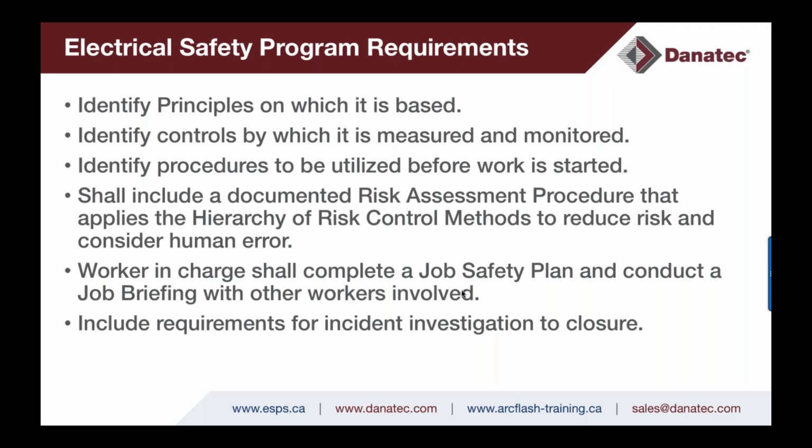The electrical safety program should include requirements for incident investigation to closure. So I find that this is not effectively managed. Companies do have overall incident management systems and their overall OHSMS systems, but what they lack is any electrical hazard content in the overall IMS. I see this over and over again.